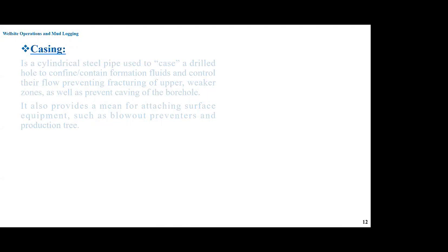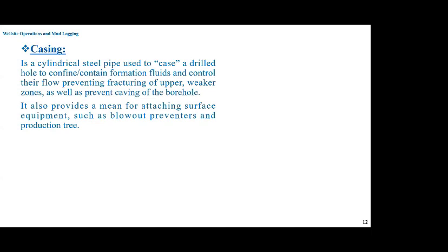The casing: after drilling is finished, then they start casing the hole, to contain the formation fluids and control their flow. Also to protect the upper weaker zones and prevent caving of the hole.